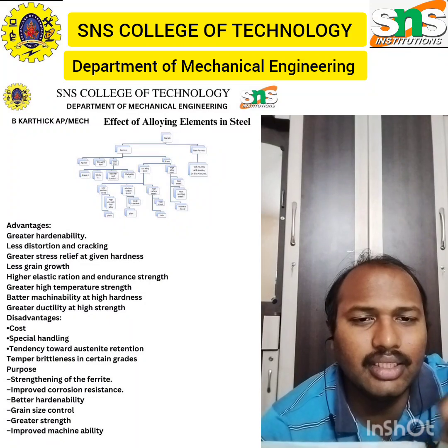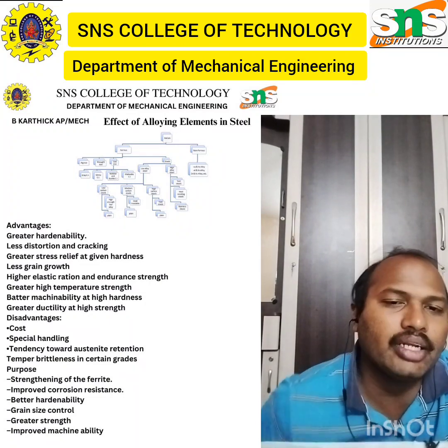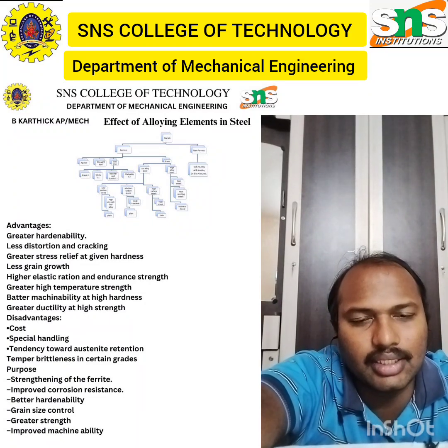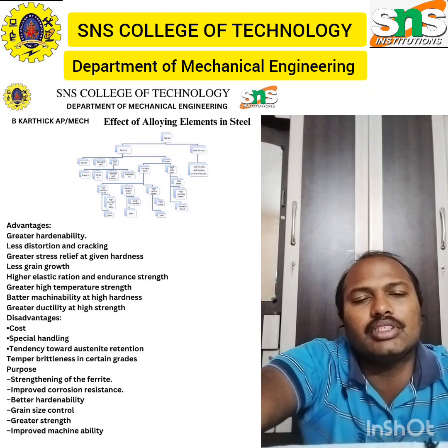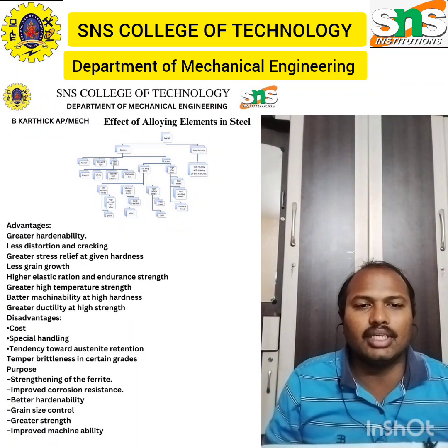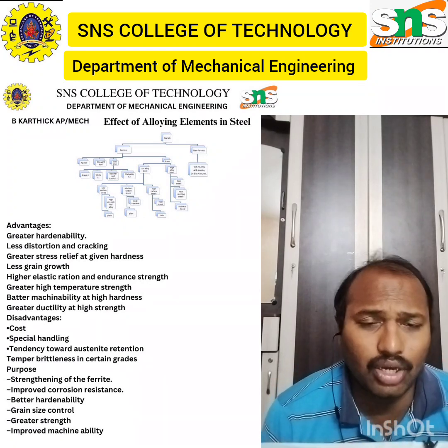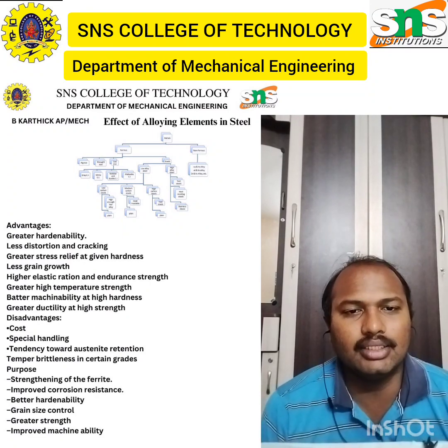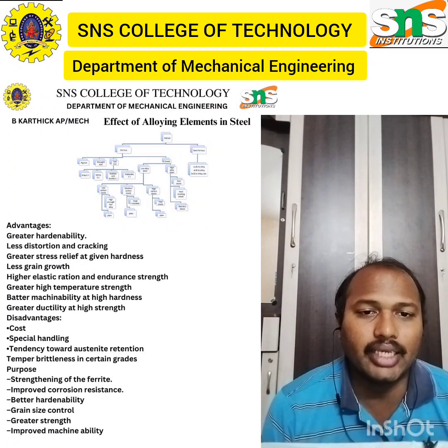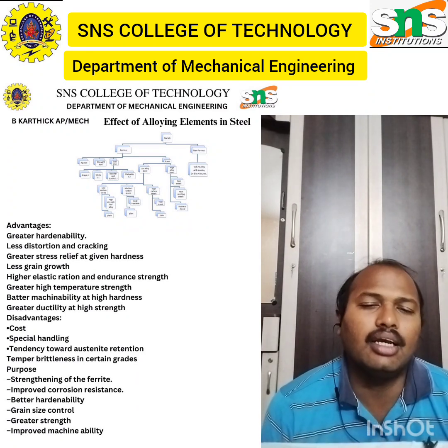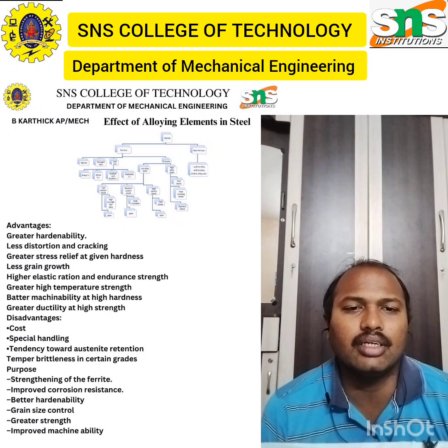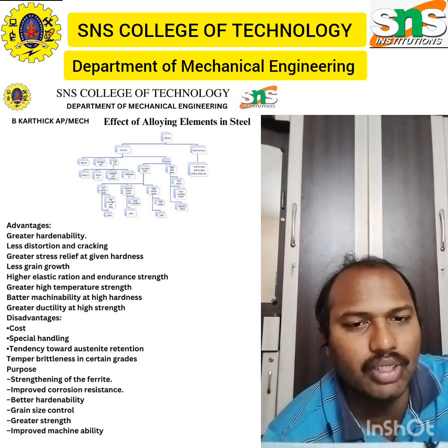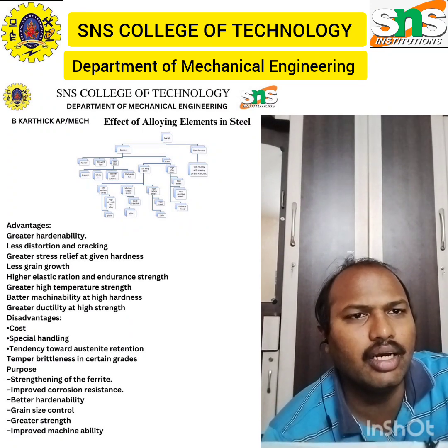As we spoke before, HSLA steel or Maraging steel are employed in certain applications due to their alloying addition only. HSLA steel is used in structural applications because of its alloying addition. Maraging steels, which have carbon, silicon, molybdenum, and nickel, are used in applications like landing gears, rocketry engines, and teeth of crushers. So alloying addition helps a particular steel to be used in different applications.